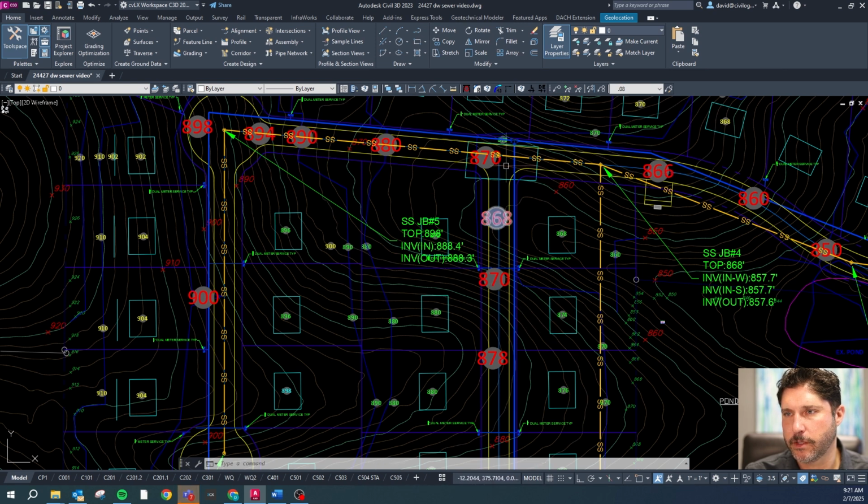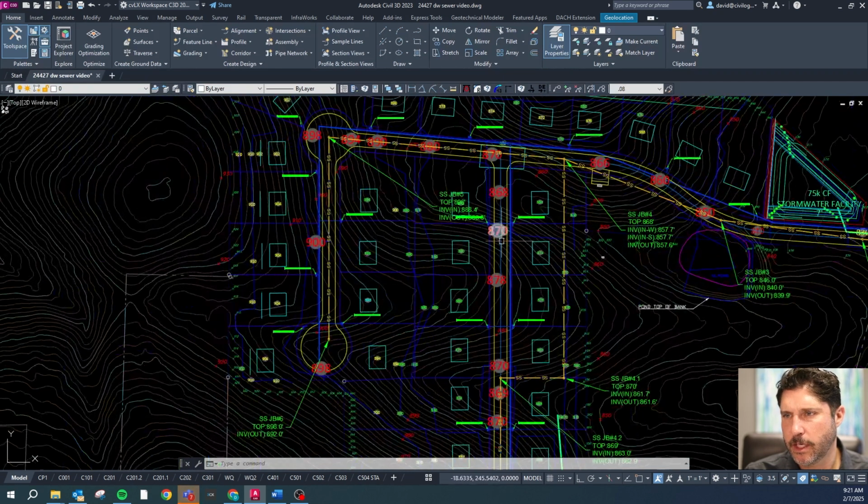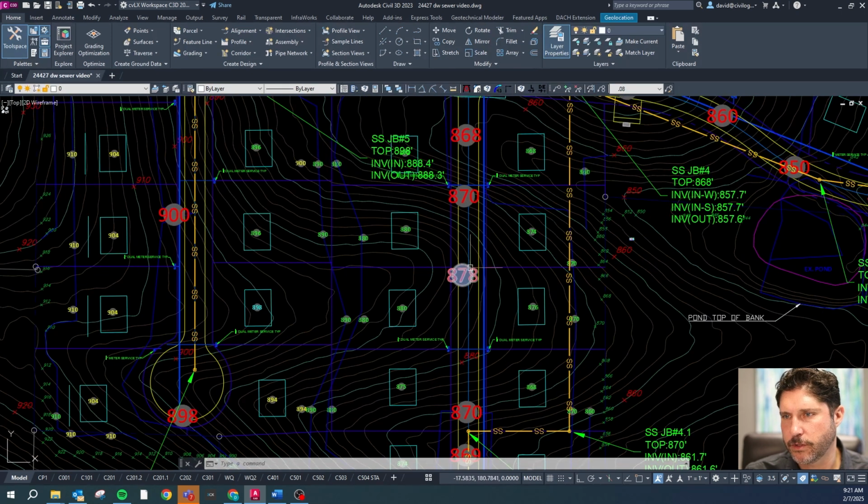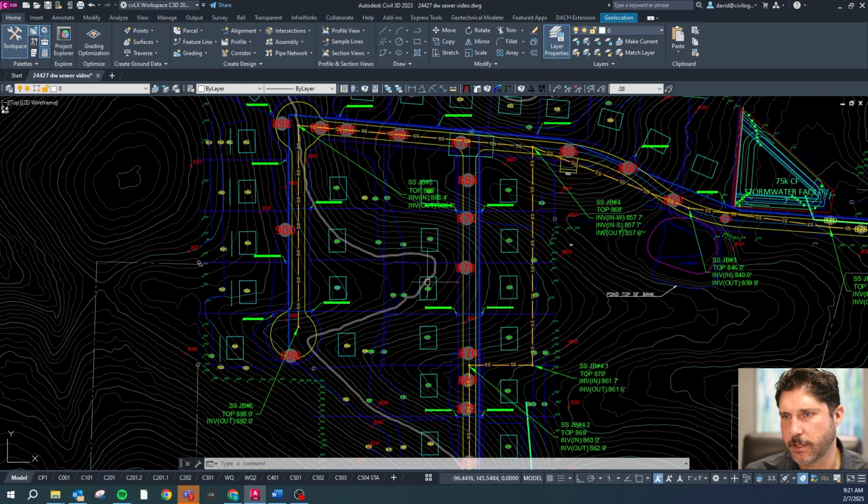Trying to think where we want to put this manhole. We could do a little line coming down this way, so all of these houses can easily connect to this. This house can easily connect to there. This house can easily connect to here. But we are kind of leaving these two guys hanging. I almost wonder if we should just drop another structure in this way and come in between these two lots for these two guys to connect. And that would be shorter than going this way.